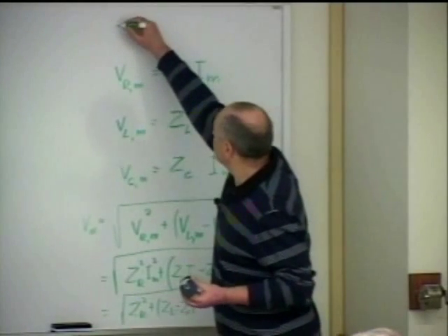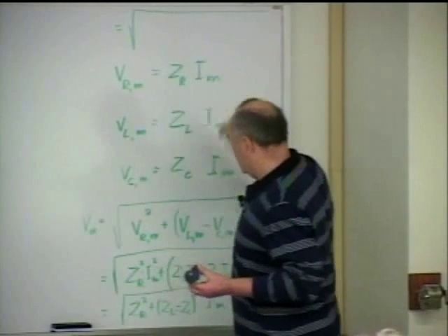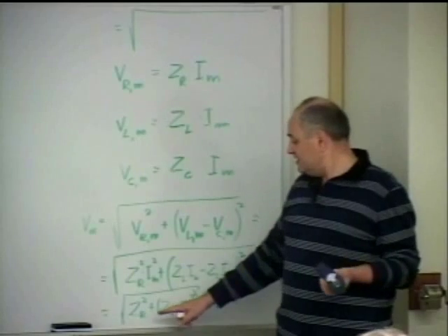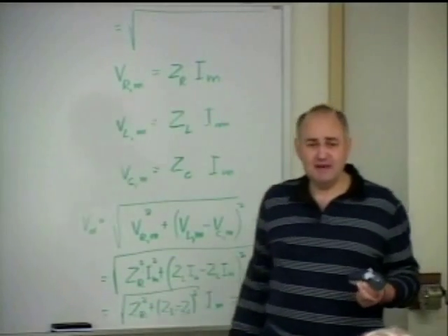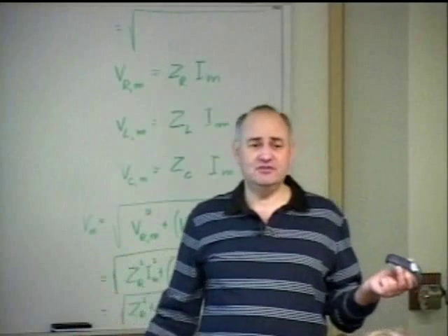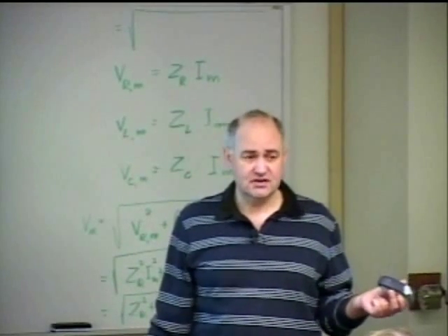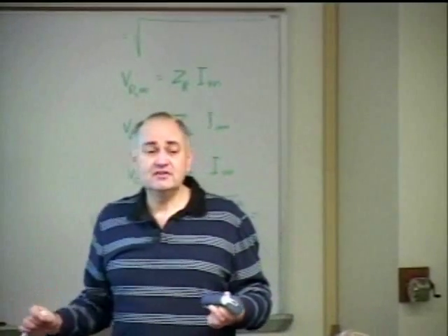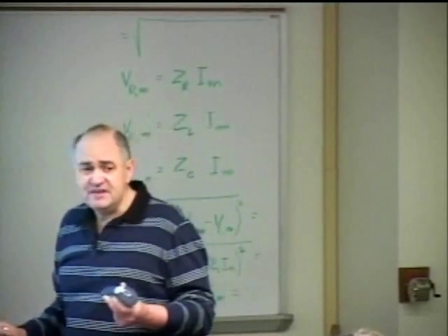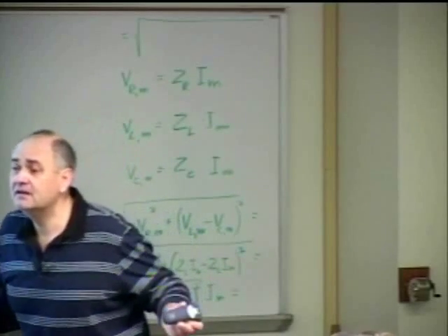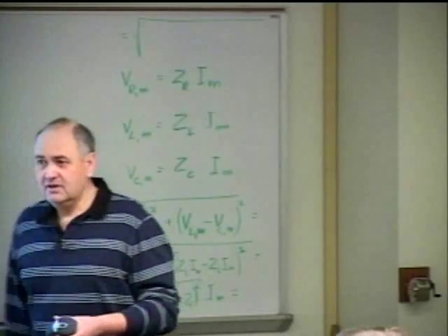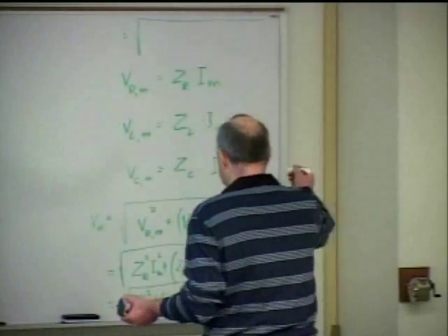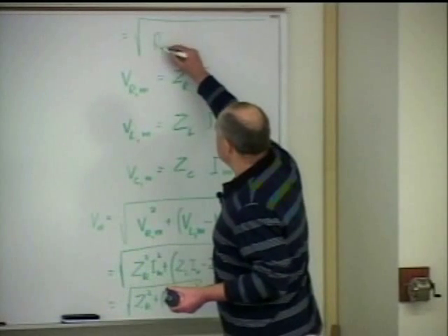So how is impedance related to resistance? They are equal, correct. So here I have the square of resistance plus the impedance of the inductor. If you go to a shop, you will ask for an inductor with a particular inductance, because impedance happens to be a function of angular frequency. So what is the impedance of the inductor at angular frequency omega? Omega L.